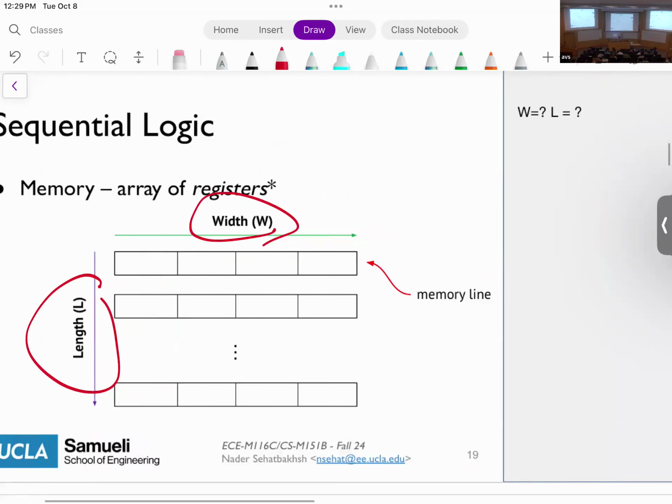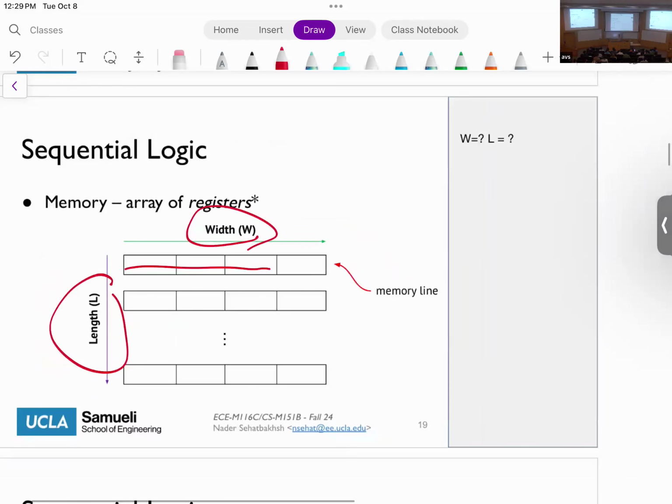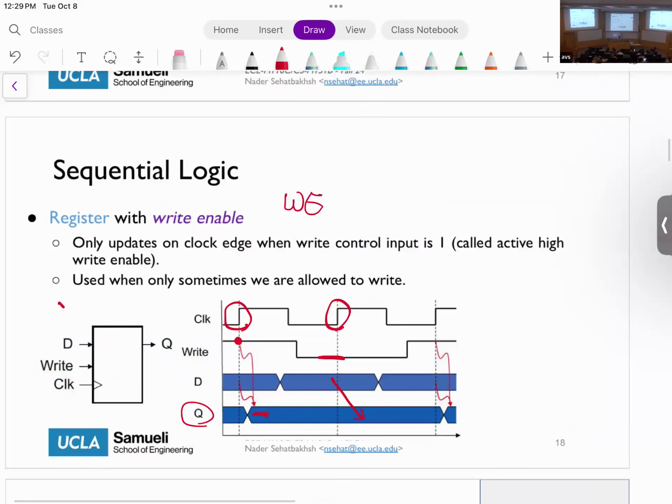And each one becomes essentially one register, okay? Your DRAM or your SRAM is not based on registers and flip-flops. They use a completely different technology that I'm going to talk about later. But your register file is essentially an array of these single bit registers that I showed you here. So each one bit is something like this, okay?